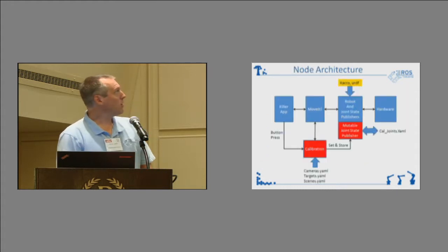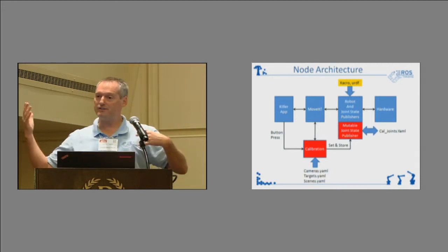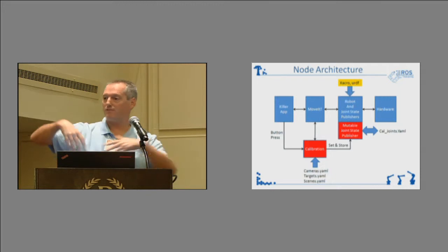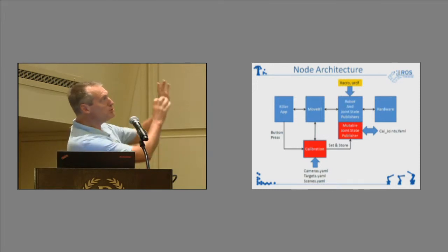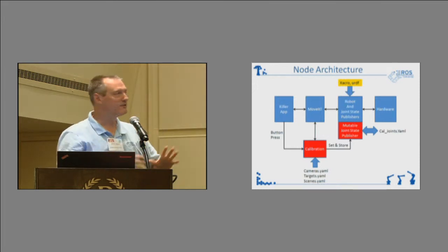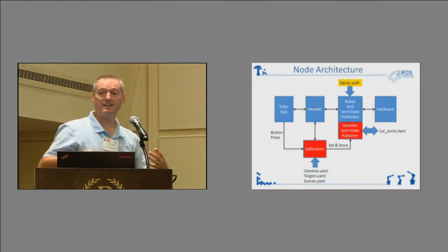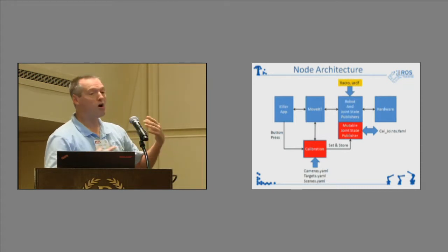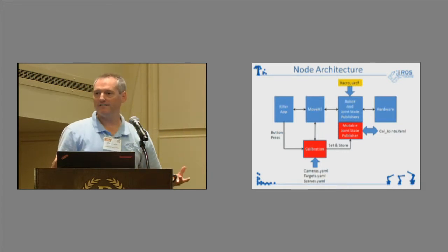Okay, so how does this all fit together? We envision somebody has a killer app that allows them to scan a bunch of parts going into a paint booth and have the robot automatically paint them. So they're talking to MoveIt, and all the blue objects are standard stuff. You've got a robot and a joint state publisher that's keeping track of where everything is. All that is powered by some Xacro file that generates your URDF.